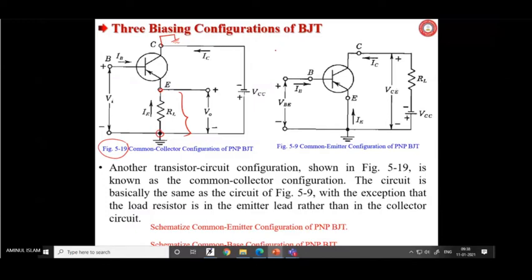Suppose you have a current source and you want that current should be zero. What you can do? You just open it. You just remove it, and the resistance here is then infinite. So for the case of a current source, it has to be removed or opened.